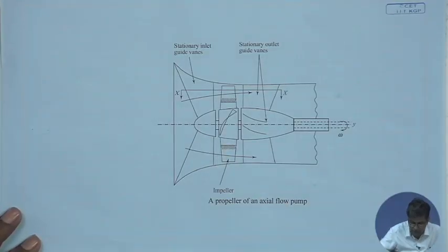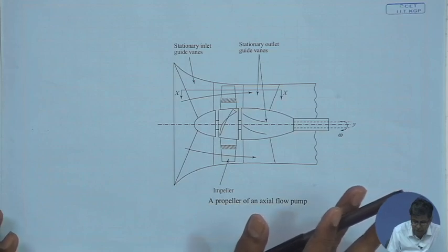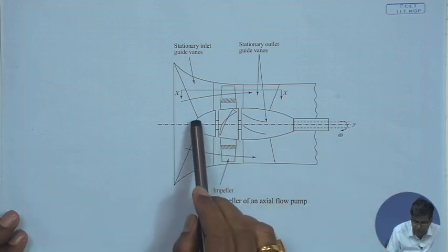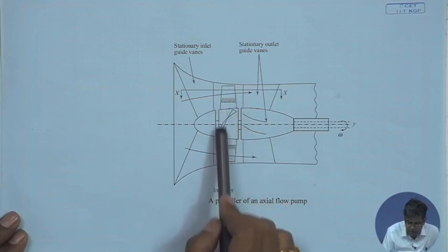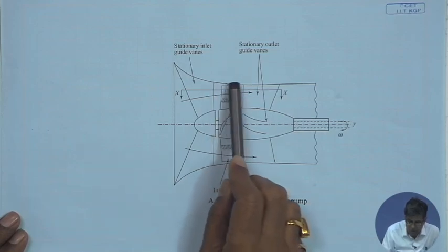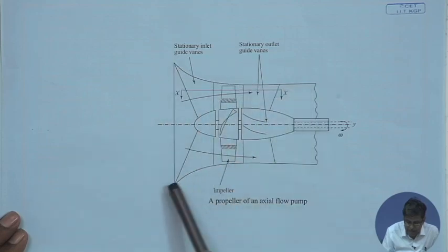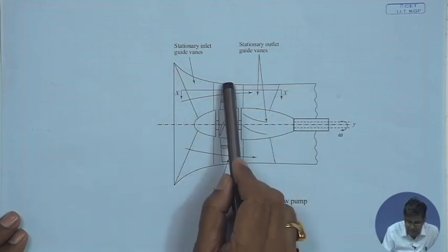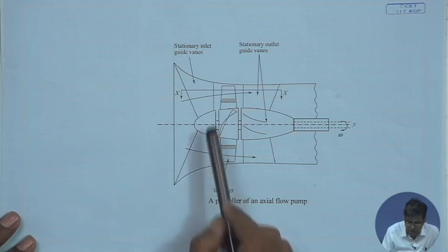Now, the axial flow pump looks like this. Basically, this looks like the converse of an axial flow reaction turbine. It consists of a central boss, or hub, on which the rotor discs are mounted, and this is a cylindrical casing, and there is clearance between this rotor and the casing. This clearance should be made as small as possible to avoid leakage.